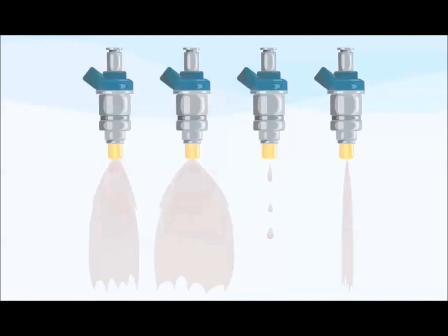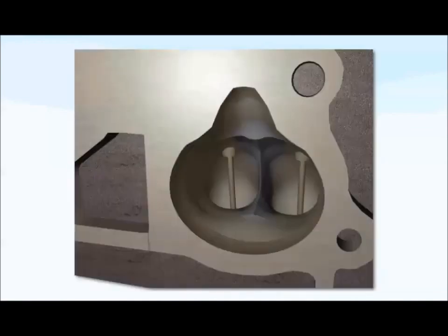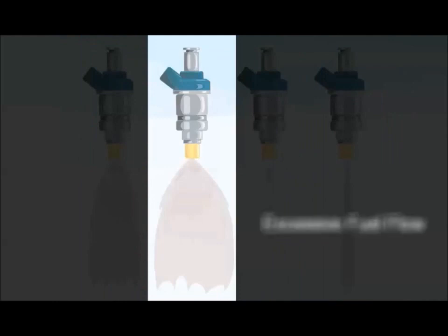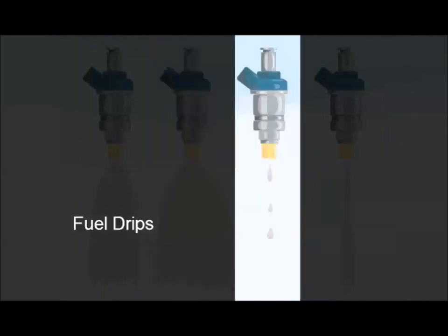Certain injector mechanical failures can cause a rich or lean code. When this occurs, a visual inspection of the intake may quickly identify the problem. Defects causing DTCs allowing excessive fuel flow, or bad injector seals, which allow fuel to flow with the injector turned off.